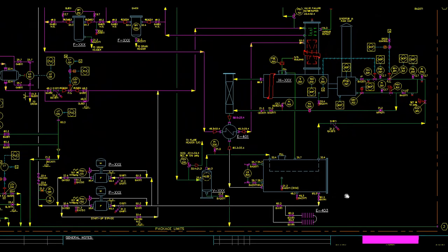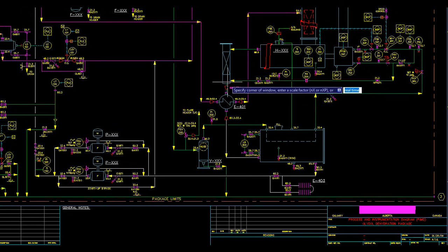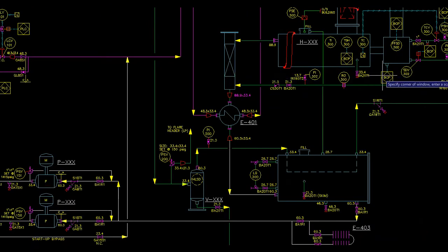Lean glycol flows out from this 3-inch nozzle to the stripping gas column. A small amount of fuel gas injected at the bottom of this column will absorb any moisture remaining in the glycol phase.